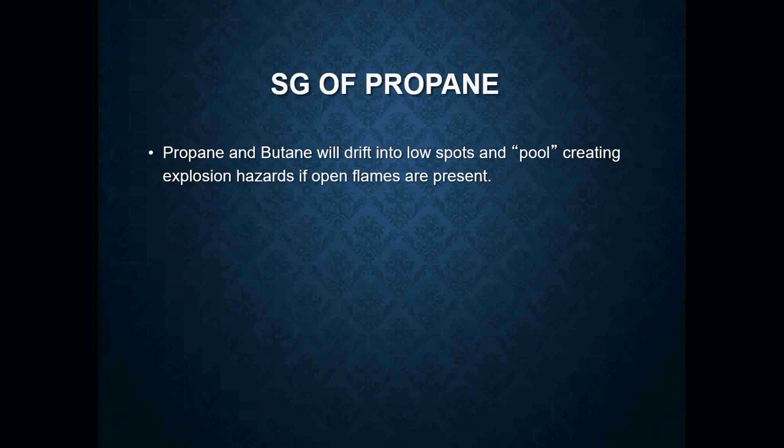can happen with pooling of propane because of the failure to find propane leaks or failure to even check for any sort of leaks. As an HVAC mechanic, it is actually very good practice to spray all of your gas fittings and gas piping with some soap bubbles on all of your joints to see if there is any sort of leaks.